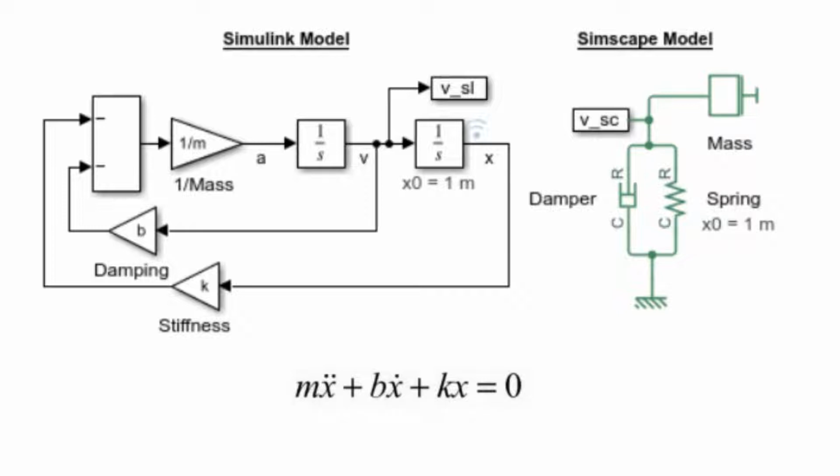Physical connections make it possible to add further stages to the mass spring damper simply by copy pasting. Input-output connections require rederiving and re-implementing the equations in the Simulink model, which might be a difficult task.